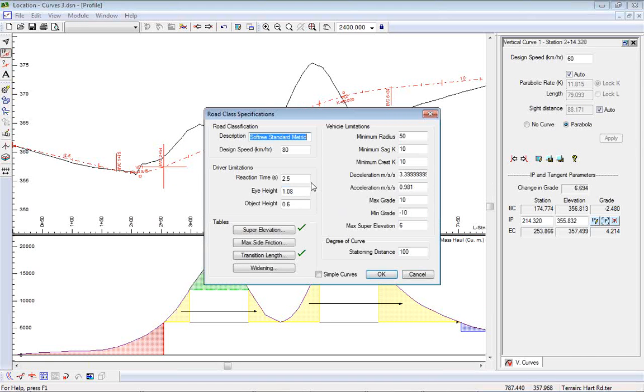based on, first of all, the design speed, that's critical. Stopping distance depends on how fast you're going, how long it takes you to hit the brake, reaction time, and your deceleration rate. Now, the deceleration rate here is in meters per second squared, which is not a very nice unit. That seems to be the standard that you find in the various design manuals.